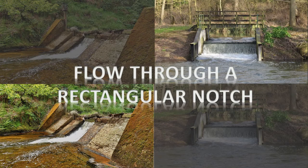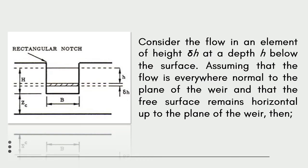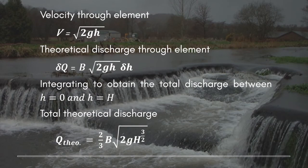Now introducing the flow through a rectangular notch. Consider the flow in an element of height delta h at a depth h below the surface. Assuming that the flow is everywhere normal to the plane of the weir, and that the free surface remains horizontal up to the plane of the weir, then the velocity through the element is equal to the square root of 2 multiplied by g and h.